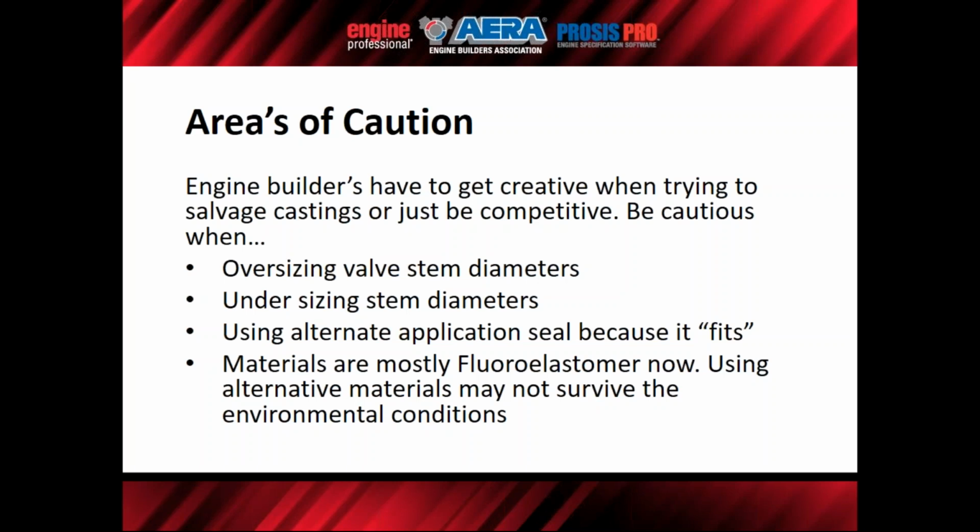There are some rough numbers. A lot of the stem seals can have 40 thousandths interference on a garter spring single lip style. But you just can't take that number and say, I'm going to use that across the board on everything. Maybe that ring and band design, which could also be inserted into a top hat, maybe it doesn't like that. So, you just have to be really cautious about that.